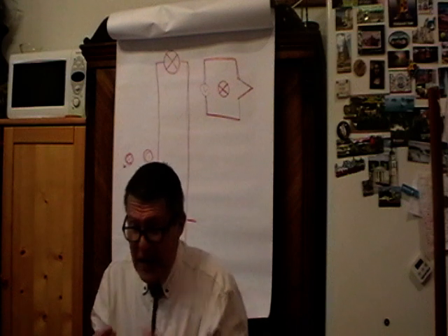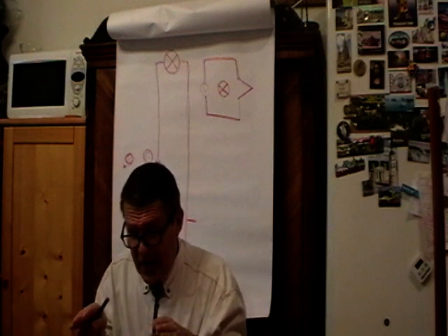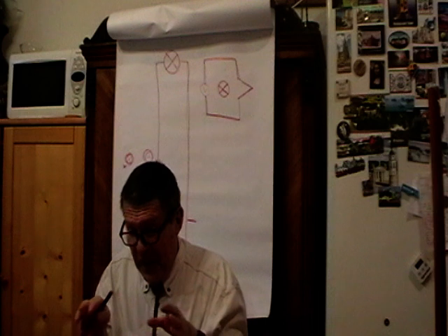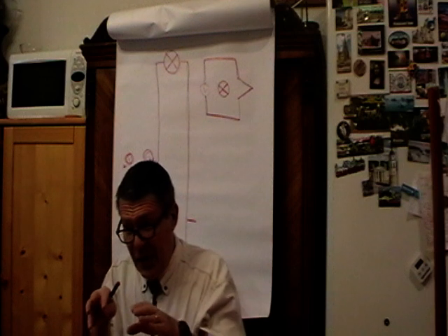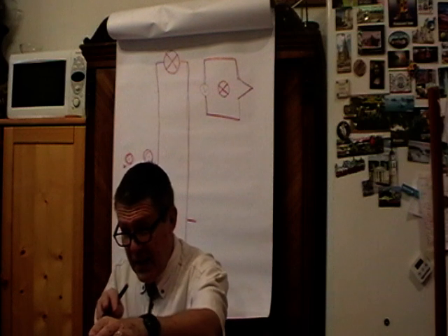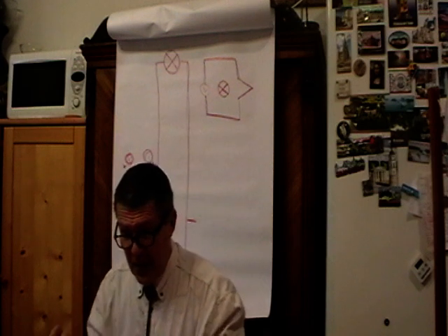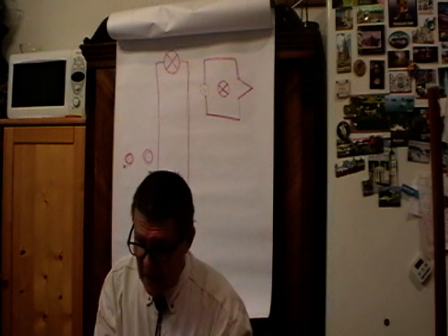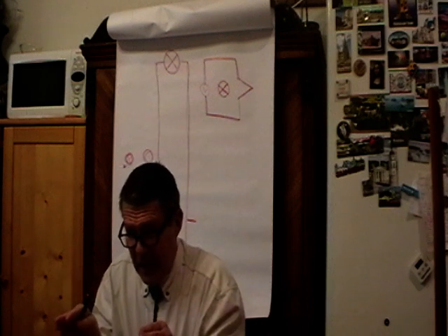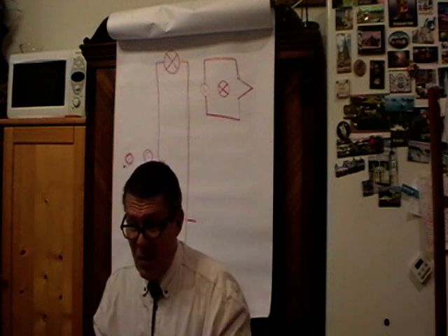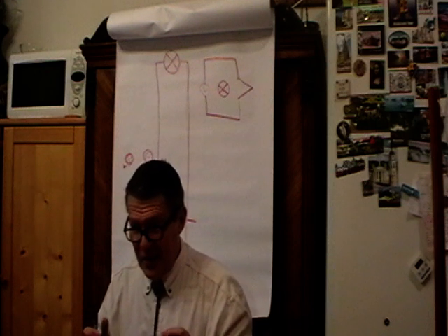So the voltage is possible due to charges that sit on those two conductors. And if we have a transmission line, they do not simply sit there. They are moving. The positive charge is moving towards the load, and then it returns back. So we have there a set of charges that create magnetic field and electric field. Electric field just by sitting on the conductors, and magnetic field by moving, which is called current. Now we a little bit understand the transmission line.